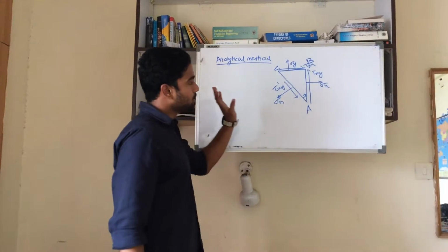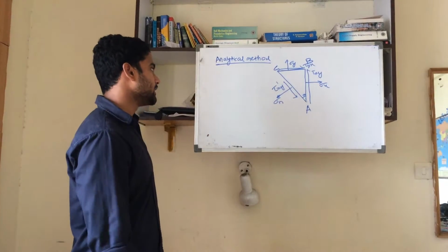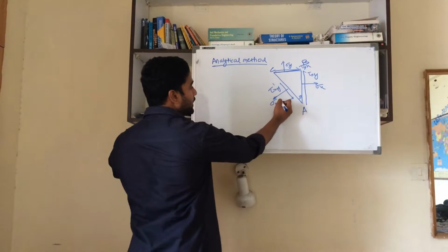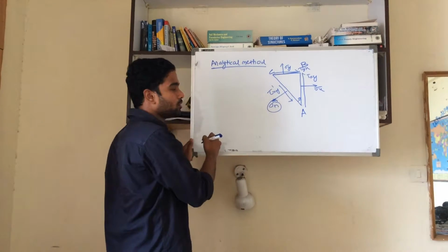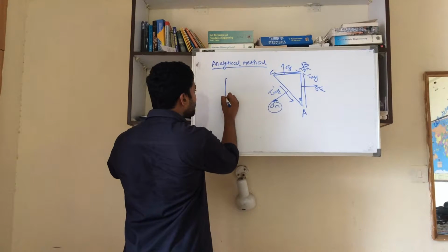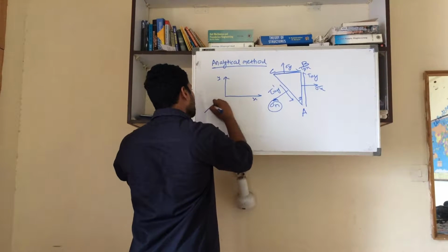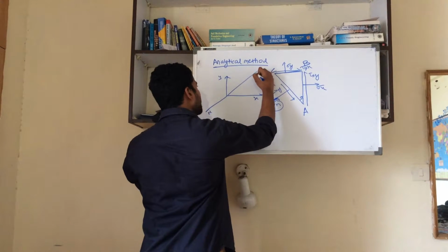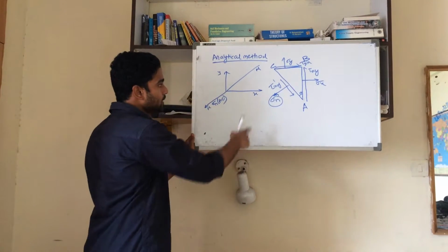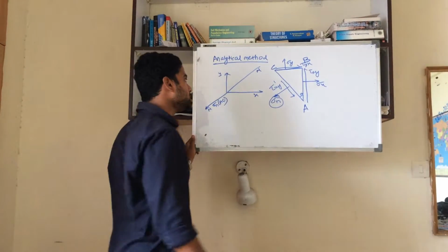Normally, to calculate the stresses, we take the force equilibrium equation in any direction. Here we will take the force equilibrium equation in the NN direction, which is the direction of the normal stress, and the TT direction, which is the direction of tau xy. Take this as the x, y axes, and this as the n direction on which sigma n is acting. Considering unit thickness of the element, the force in this direction would be sigma n multiplied with AC.